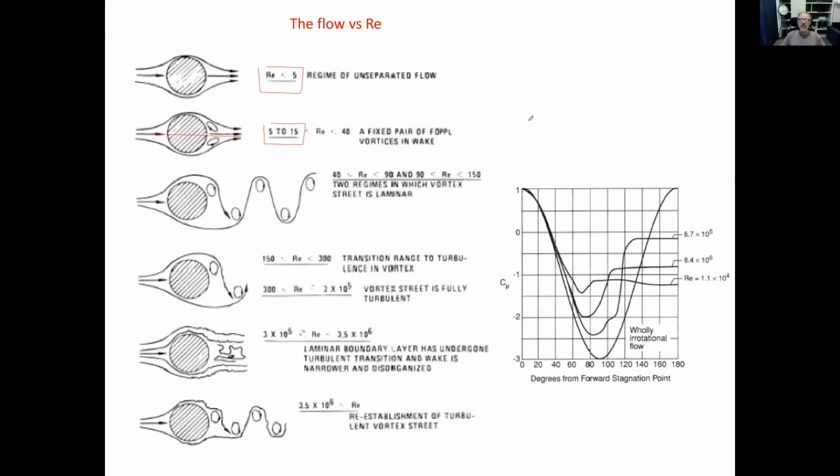Now, remember I told you the story about the boundary layer, that you have a shear here, and then you create little vortices, and then eventually there are too many vortices inside, and then they start giving velocity in all kinds of directions and the flow transitions. So similar thing. Initially, this is laminar flow. You get too many vortices from here and here, and then they grow. They just cannot sit together. So they start alternating, going left and right, and you get this thing which is called the Kármán vortex street, the vortex shedding. Okay, and it keeps on growing, and then at 150, 300, you don't see much difference.